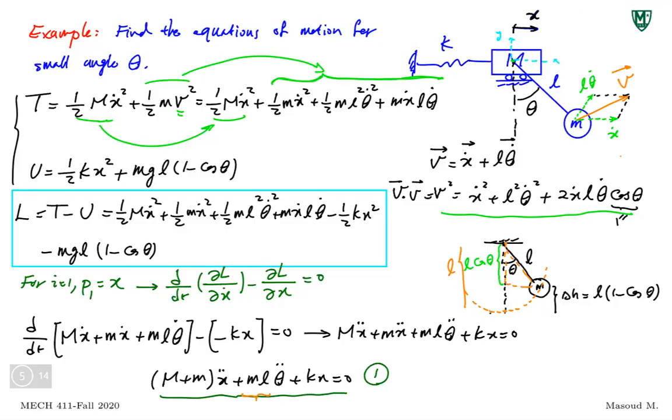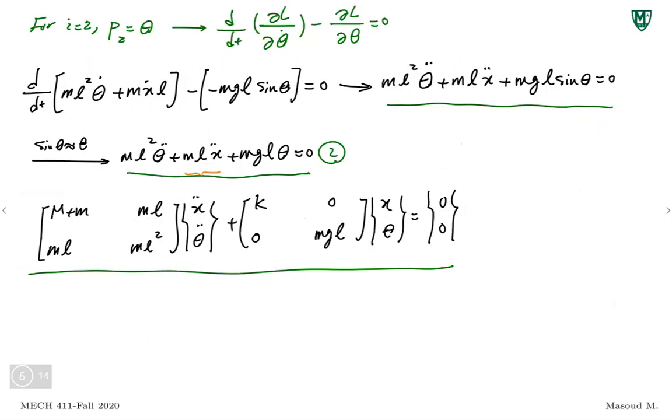It might be because of the mass matrix, and there are cases where both of them are causing the coupling. You have a mass matrix that is symmetric, but its non-diagonal elements are 0 like this, and at the same time your stiffness matrix non-diagonal elements can be non-zero. So both of them are creating this coupling situation that's making our life difficult to solve the equations of motion.